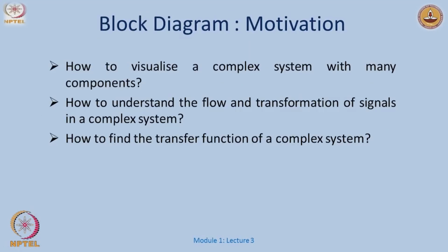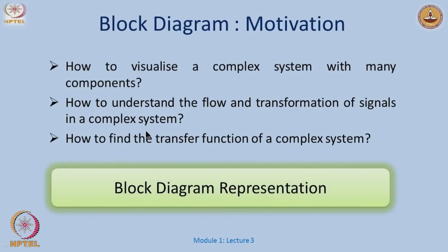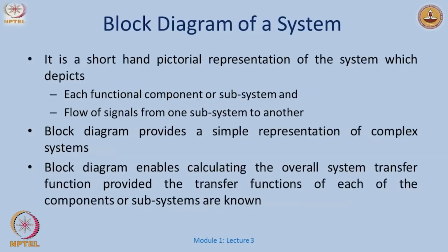Okay. The second thing is, if I have a system with different components, how do I visualize it? Is there a nicer way to represent that system, and to understand the flow and transformation of signals in a complex system? Or given a series of interconnected systems, how do I find the overall transfer function? We will try to understand that a bit, and this is what we usually call the block diagram representation. Okay. So, what is a block diagram representation?